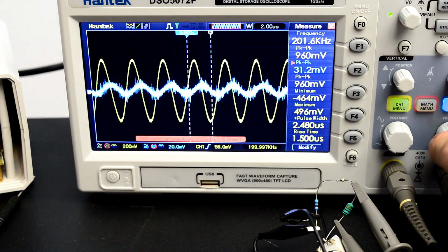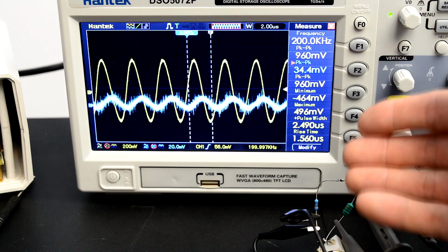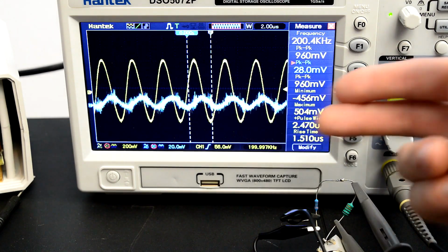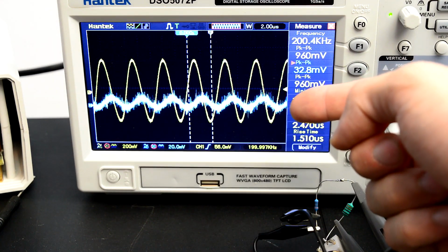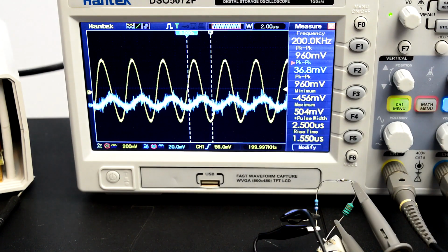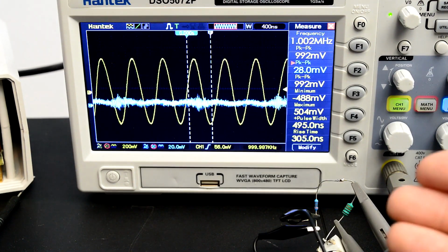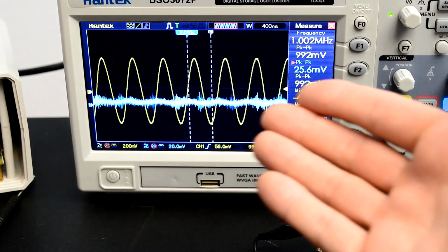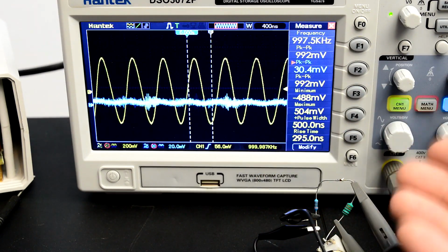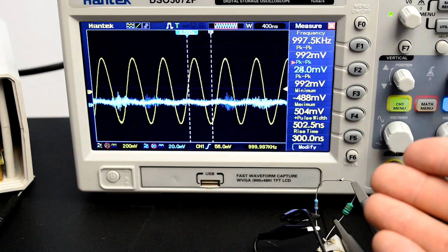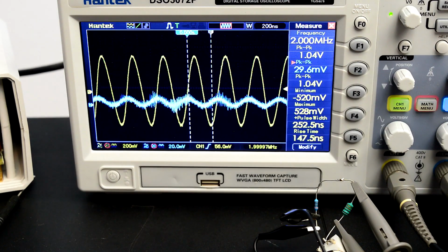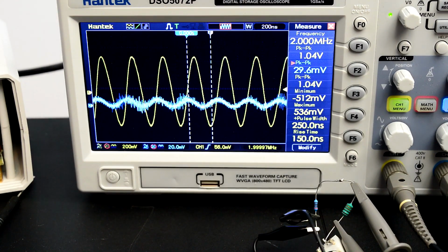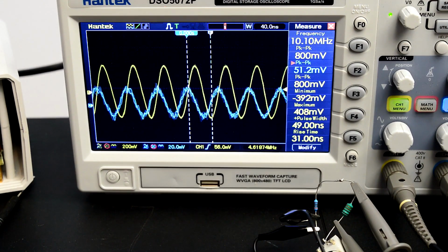So let me just increase its amplitude a bit. Right now the voltage scale for the output signal is 10 times smaller than the one for the input. We've got 20 millivolts per division for the blue signal, 200 millivolts per division for the yellow signal. We've reached a point at which we can almost no longer see the signal coming out of the filter, so the filter has completely attenuated the input signal, and now the signal is coming back. We're at 2 MHz and we can clearly see that the output signal is making a comeback. And again, with increasing frequency comes a higher signal.